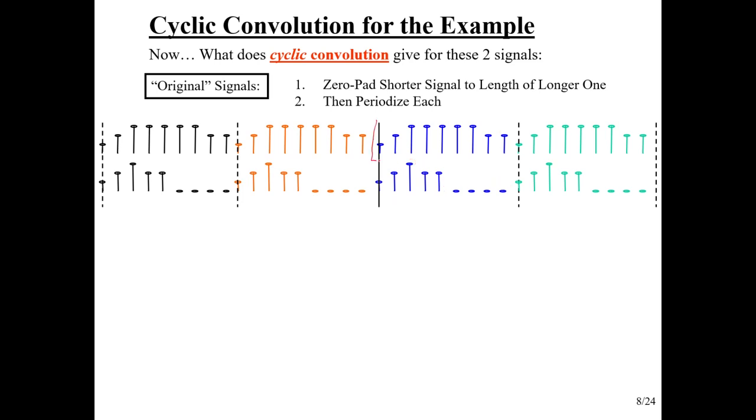And now I could do a DFT of that and a DFT of that, do the product of them, do the inverse DFT, and we want to see what we get. And our theory that I stated on a previous slide, we didn't prove it, but I'm just stating it. The theory says the result of that is circular or cyclic convolution. And this is what you would get.